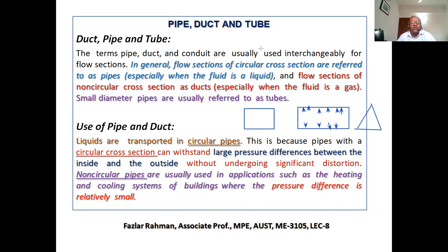And if you think of this small section at the upper portion as a distributed beam with support at both ends, then what will happen? You get support right over here, support right over here, right? And outside, what pressure do you have? Outside, you have atmospheric pressure, but atmospheric pressure is low, right? So in that case, this edge will deform like that.